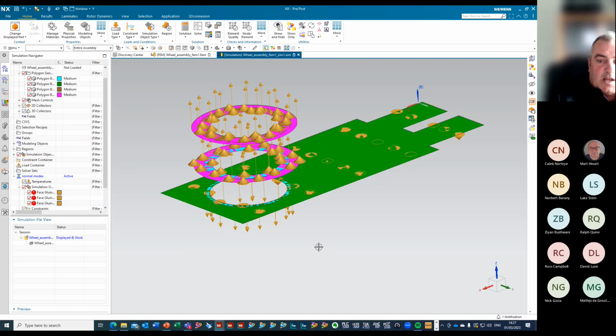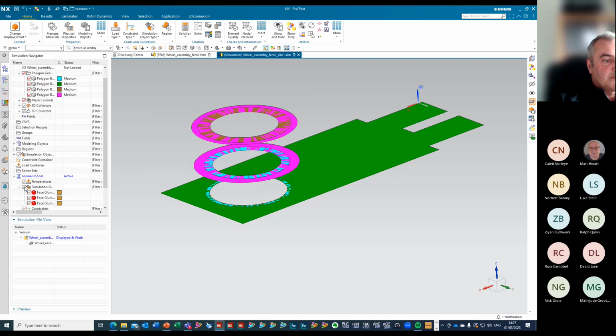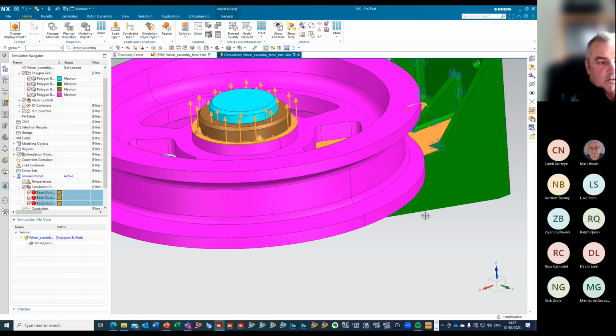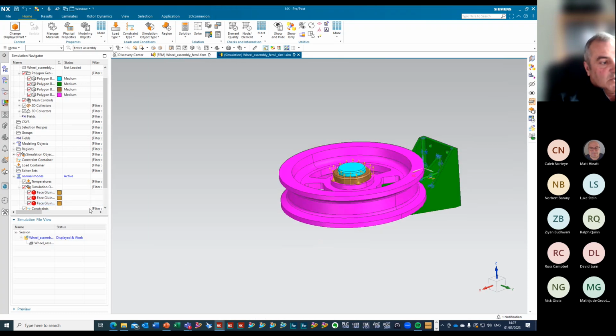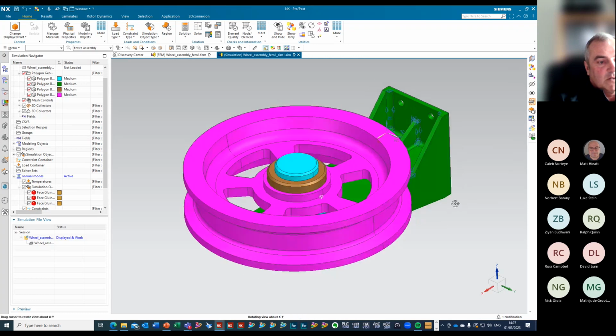So now I've put gluing in between all of those surfaces where it's clamped down by my locking nut on the top. And they were automatically created for me, but I just told it what surfaces I wanted to consider. If you do Control Z, you'll get back to what you had, and if you don't want them on the display again, you can just switch them off.